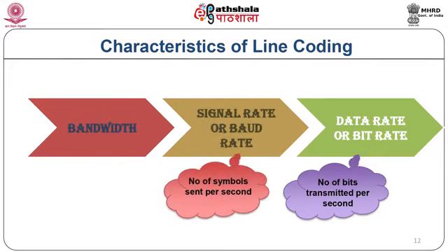Baud rate is the measure of signaling elements or symbols sent per second. A symbol in some cases would be a binary logic level 0 or 1. In that case, baud rate is equal to bit rate. In other cases, the symbol is one of several discrete signal amplitudes or phase shifts, each representing 2 or more data bits.